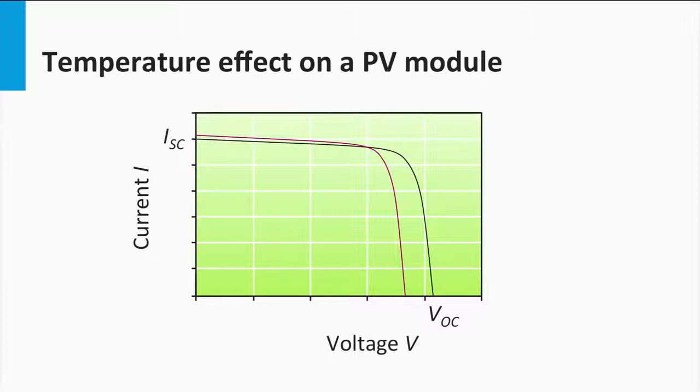On the other hand, if the temperature were to decrease with respect to the original conditions, while the irradiance were constant, the PV output would show an increase. The minor increase in current with temperature can be explained with the fact that carrier concentration and mobility increase in the semiconductor with temperature. This is consistent with our basic understanding that a semiconductor, unlike a regular conductor, exhibits better conductivity with increasing temperature and is a perfect insulator at absolute temperature of 0 Kelvin.